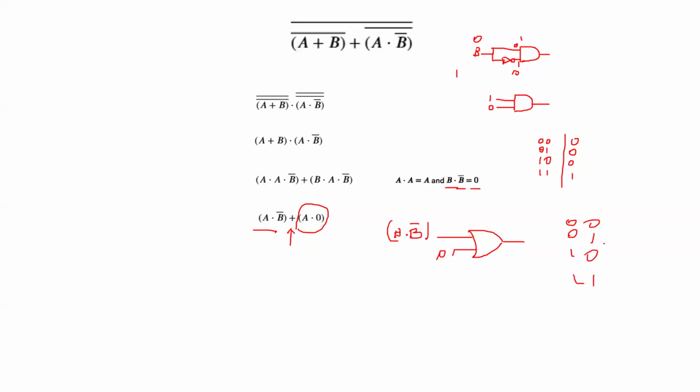The OR gate truth table is, is one of them active? Yes, so it's OR. Either this or that is going to give us 1. So if we have a 0 here, and if this whole thing becomes 1, then we're going to have 1 on the output.